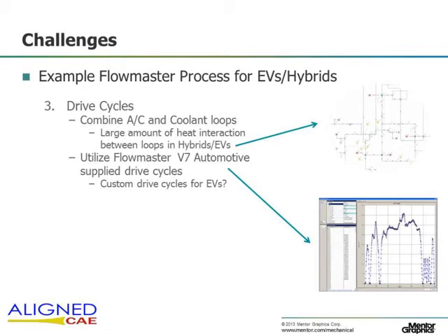So that's already in FlowMaster. We also use that information, put that into a powertrain cooling simulation to extract our heat rejection curves over that same drive cycle. We use all this information, we pull it all together, we put it into FlowMaster, and we run a transient simulation over a drive cycle. Over this drive cycle, what we're varying is things like heat rejection from the motors. We're also varying front-end airflow because the vehicle speed is changing over time according to the grade and acceleration requirement of the vehicle.